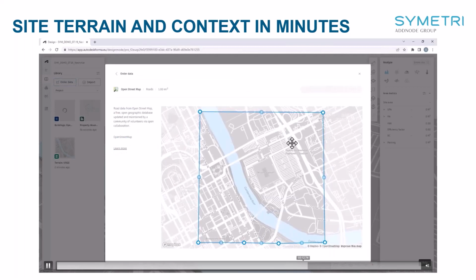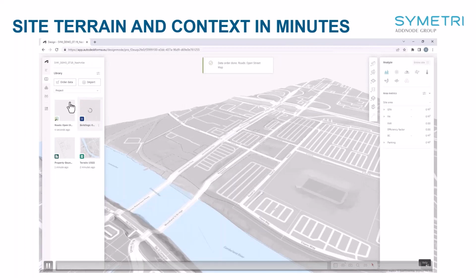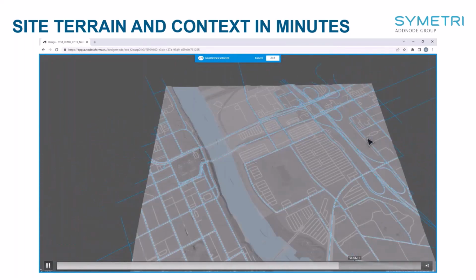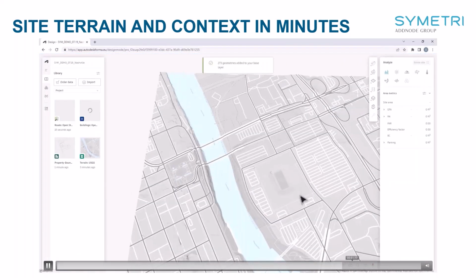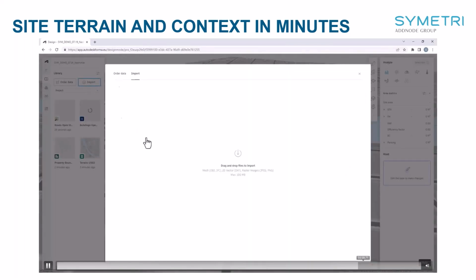So next, while buildings are still loading, we're going to do roads. So again, it saves our boundaries and we can click OK once it loads. And this will be, like I said, the roads from OpenStreetMap. These are only lines. They actually come in pretty quickly. All right. And again, we have the ability to be selective or window select and add them all to your project. Now, what's important about roads is for the beta noise analysis, we can actually add traffic information to that. Time of day that the traffic or percentage of day the traffic is high, so on and so forth.